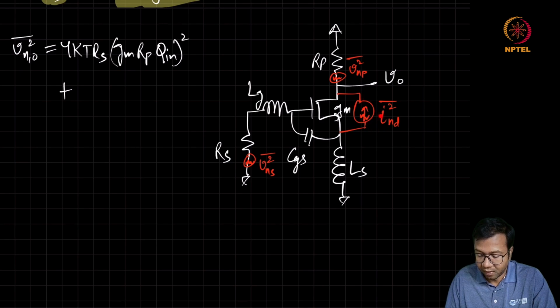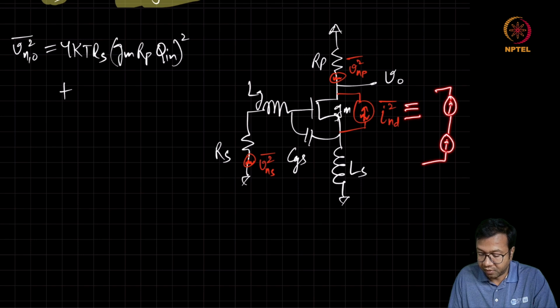for a MOSFET, where you can use two approaches. One approach: you can split this current source into two current sources in series, and then this middle node can be connected to any node in the circuit. So if you connect it to ground, it will simplify your circuit analysis, and then we can find the contribution due to each of these sources independently and add their contributions at the output finally.